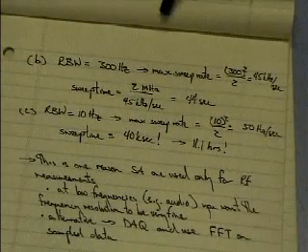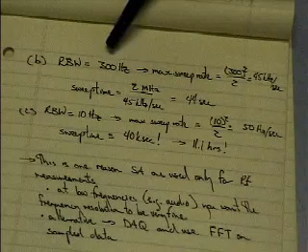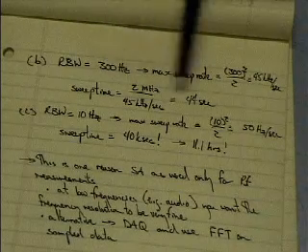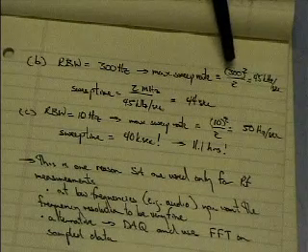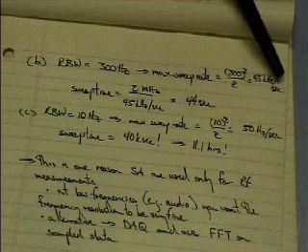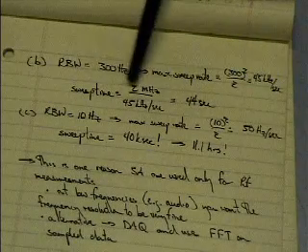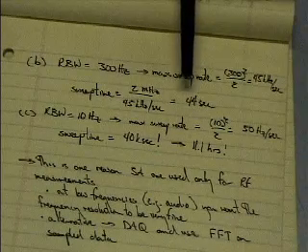Okay. Well, how does increasing the res bandwidth reduce my sweep time? Well, my sweep rate now increases ninefold to 45 kilohertz per second, which allows me to sweep across the 2 megahertz in 44 seconds. Still a relatively long time.